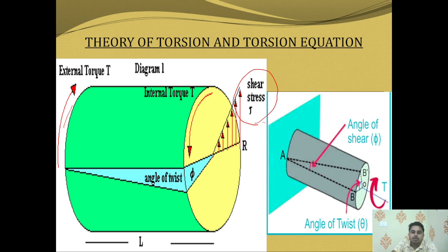So there will be a torsion, and what is the main point here? There it is, the angle of twist. And the angle from one end to the other end, whatever you say, is the angle of shear. Because of shear force, it offers these angles. If we see the second picture, there are abbreviations indicating the initial position and the after effect position, that is OB and OB dash. The angle of shear is defined by phi and the angle of twist is defined by theta.